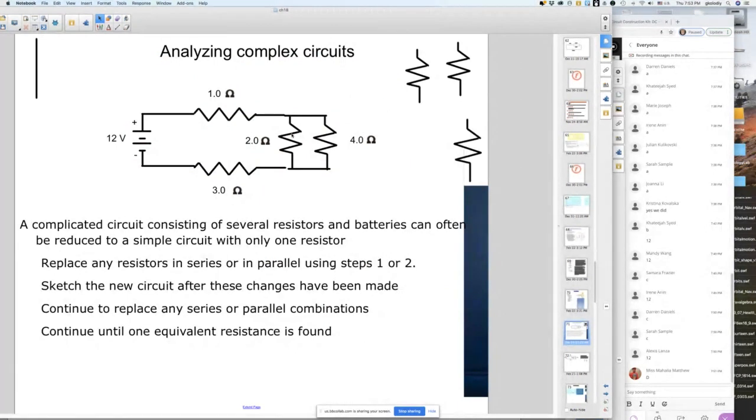So if you want to find the total resistance like this and something like this, you got to start from the beginning. You got to add all the parallels. In other words, you're going to add these two in parallel and replace them by one resistance, which you can draw here. Whatever the number is, we're not solving this problem, but 1 over R1 plus 1 over R2 equals 1 over R total, and this is 1 over R total.